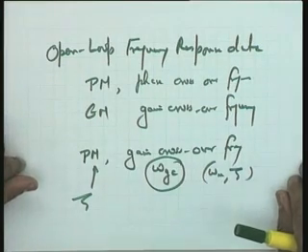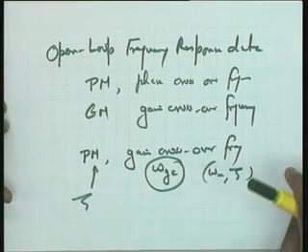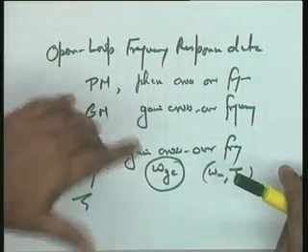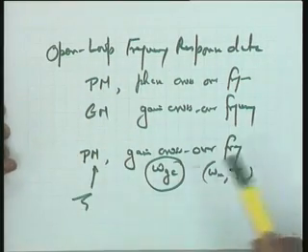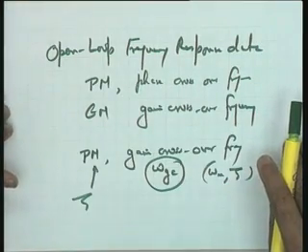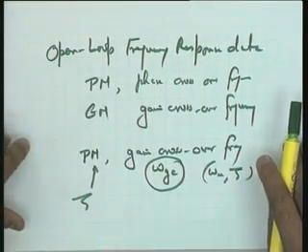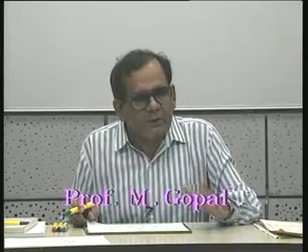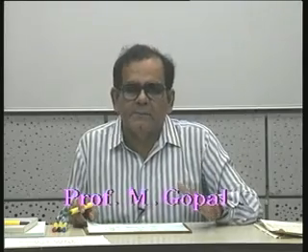from this information. Identically, if I give you specifications in terms of zeta and omega n, you can translate those specifications in terms of phase margin and gain crossover frequency, and then carry out a design in frequency domain so that the required specifications are met. Okay. This is your open loop frequency response data, and the gain margin and phase margin you can get, as you know, from the Nyquist plot or the Bode plot. The Bode plot being more convenient because construction of the Bode plot is easier.